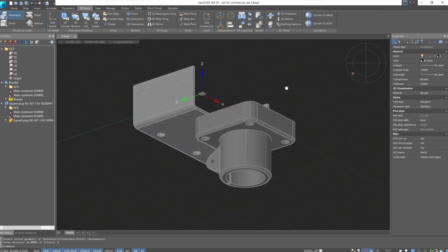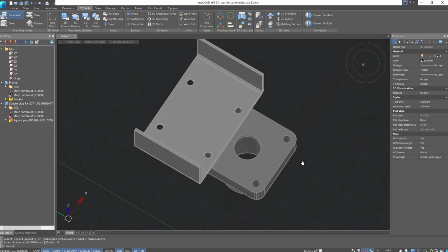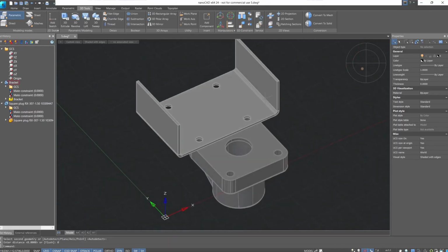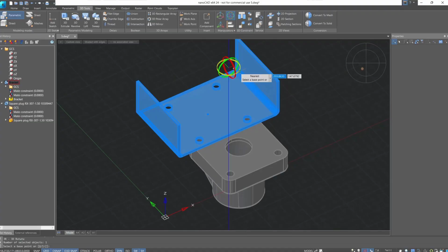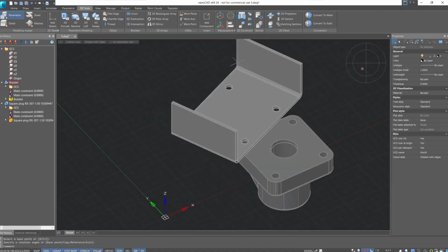Now these elements align along these planes, and considering the previous concentric constraint on the holes, these elements are now fixed by the lower plane, but they can still rotate relative to each other. For example, let's use the 3D rotation command. Since they are only fixed with a concentric constraint, they still have 1 degree of rotational freedom relative to each other. However, for mating holes in different models, it's more convenient to use the Insert 3D constraint. With it, we can simultaneously fix the hole mate and the plane of their placement relative to each other. Remove the previously created mate constraints.